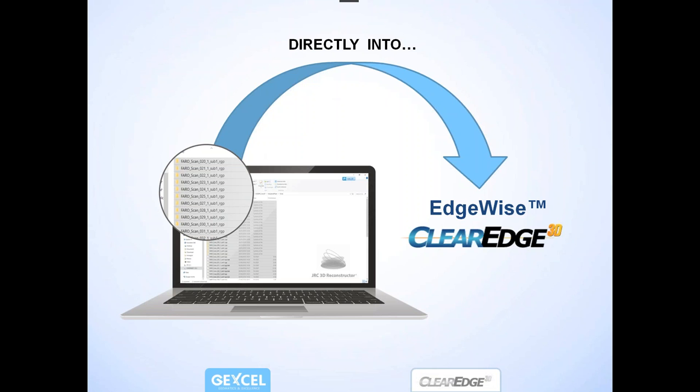The software also includes flat target detection, so you could also insert targets in difficult situations, or in any case use targets for the final georeferencing. So in LineUp, we have tried to group all the alignment steps that are typically needed in a laser scanner job.